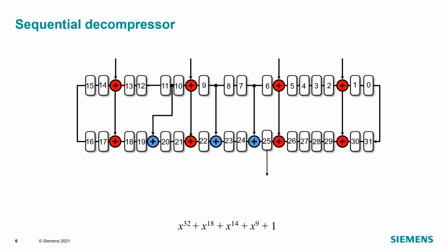A sequential decompressor has 2 parts: a linear feedback shift register and a phase shifter. In EDT, we use a ring generator as PRPG. It is faster than both the Fibonacci and Galois-based PRPG because there is at most 1 2-input XOR gate between any flip-flops, and all feedback is local. It is also more modular, and it can be easily segmented and distributed.